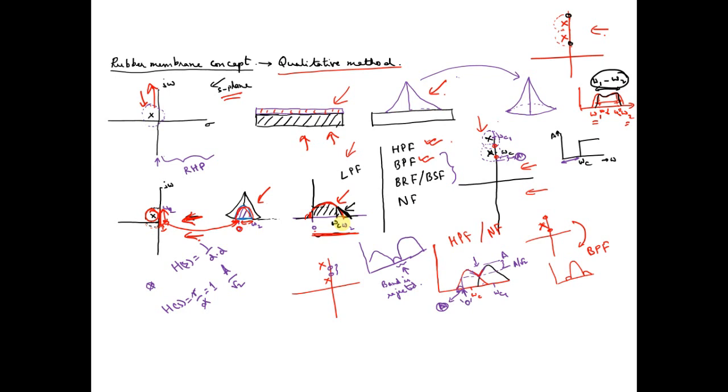Now if you place a zero near the pole, the roll off will come down quite quickly. And if you do not place zeros on the frequency axis, roll off will be as per usual. So this is how you can modulate the thing.